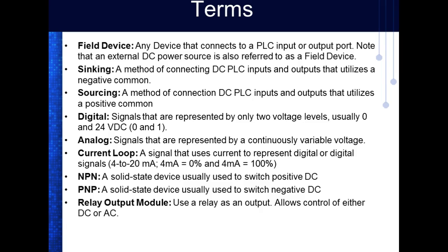Sinking, a method of connecting DC PLC inputs and outputs. Now, sinking and sourcing only deal with DC, period. So every PLC we have down there has DC inputs, so we need to understand this sinking and sourcing.